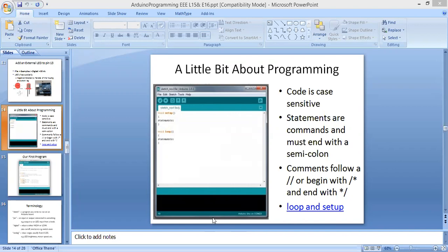In the previous session, we studied Arduino hardware and the programming. In Arduino hardware, we saw that we are using the Atmega 328 controller, which has 28 pins. And in the Arduino board, we have 6 analog pins. Here we can connect analog as an input to the Arduino Uno board. And we can assign analog input or a digital output by using the pinMode function.